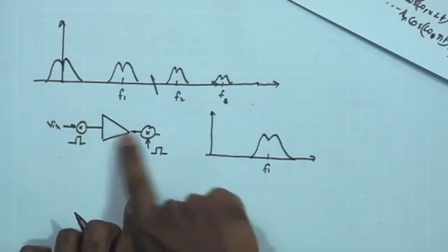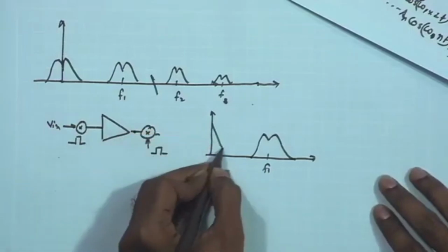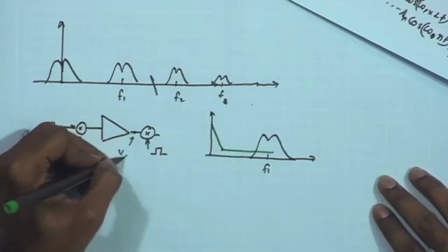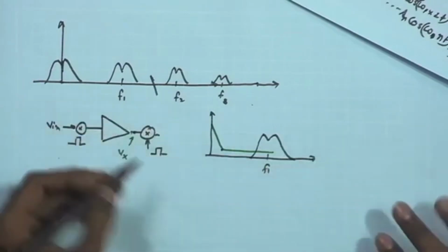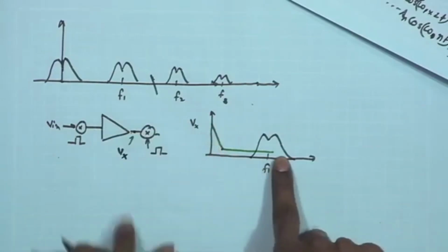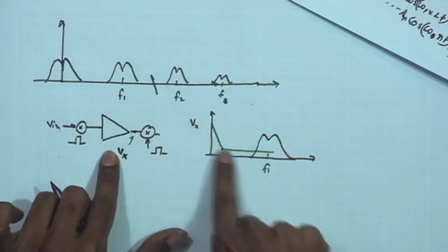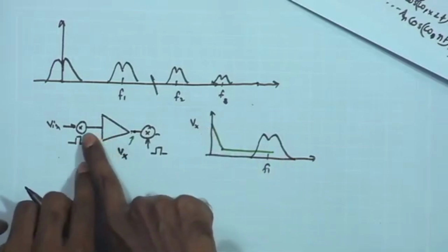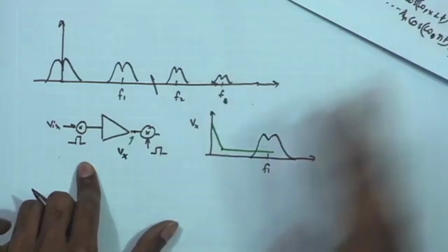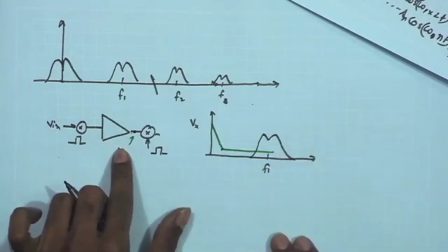also we have at this point the 1/f noise still sitting at the low value. So, I am drawing the signal Vx over here. So, this is let me call it Vx. The node Vx is having the 1/f noise spectrum still over here, because just at the output of the amplifier the 1/f noise spectrum will be as given by the original amplifier. However, the signal has been shifted towards higher frequency because of multiplication with f1, and the higher harmonics have been rejected because of the low pass filter characteristics of the amplifier or presence of a dedicated low pass filter just after the amplifier.